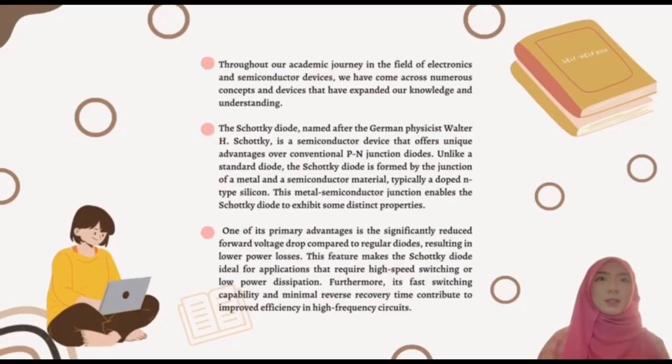Throughout our academic journey in the field of electronics and semiconductor devices, we have come across numerous concepts and devices that have expanded our knowledge and understanding. One of its primary advantages is a significantly reduced forward voltage drop compared to regular diodes, resulting in lower power losses. This feature makes the Schottky diode ideal for applications that require high-speed switching or low power dissipation.